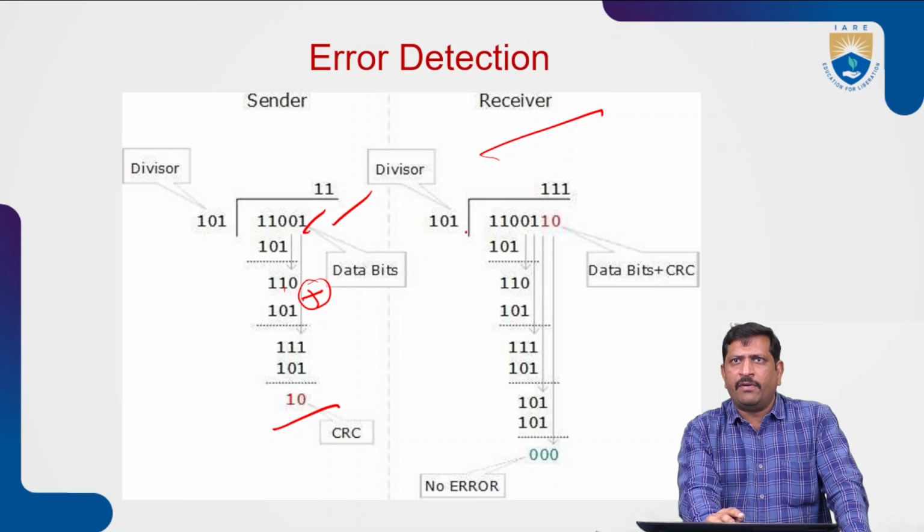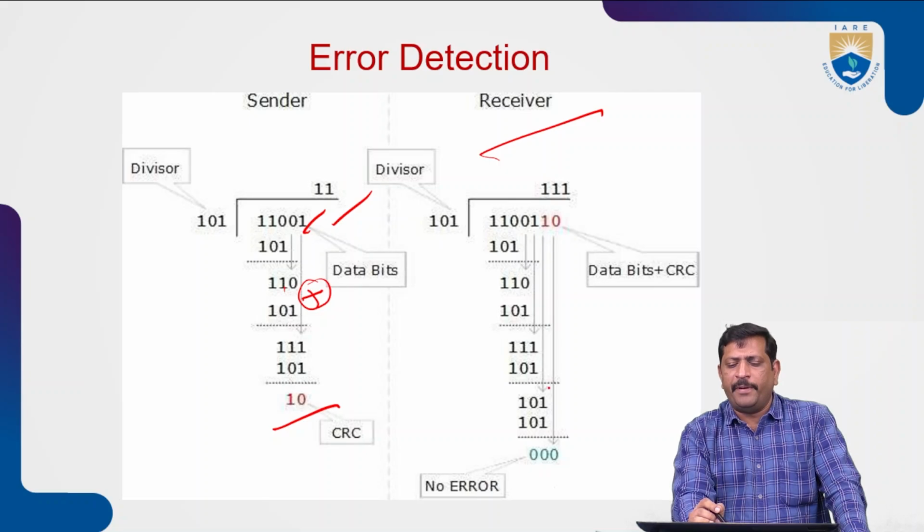And we have the result 1, 1, 0. Again, 1, 1, 0 is multiplied with 1, that is 1, 0, 1. Here we get the result by performing the XOR operation, 1, 1 as the result. Whatever result we get, the 1 will be appended here. The same XOR operation is performed here, 1, 1. The bits are the same, so the result is 0. If the bits are different, the result is 1.